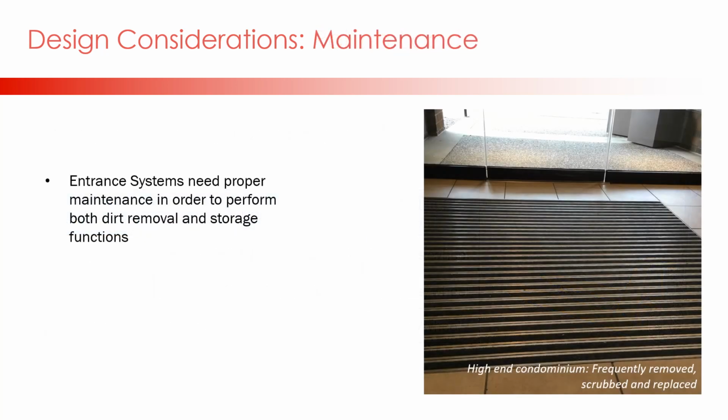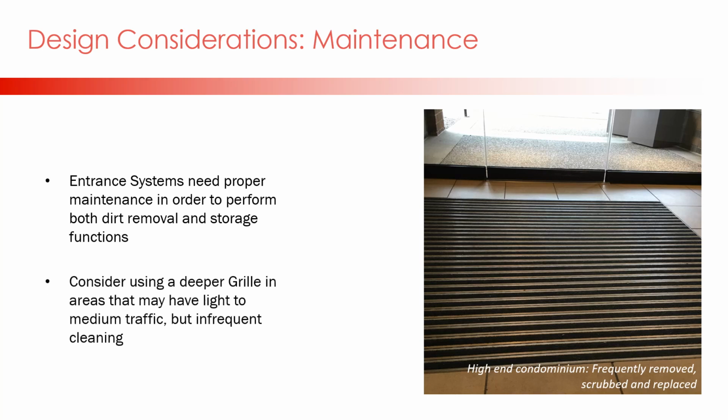A final design consideration is maintenance. Discussions with your client will provide insights on how often an owner will maintain their product. In our experience, maintenance is frequently overlooked. Once full, a system becomes completely ineffective. Providing a deeper grille will allow more time between cleanings.